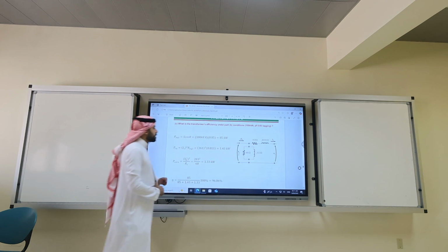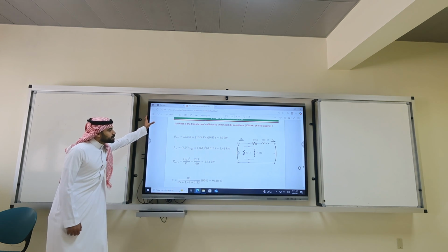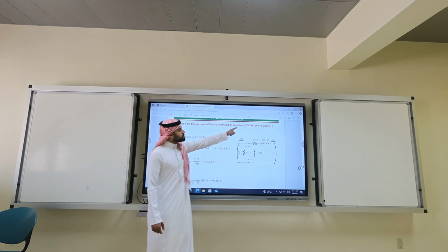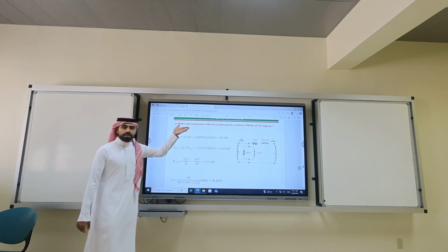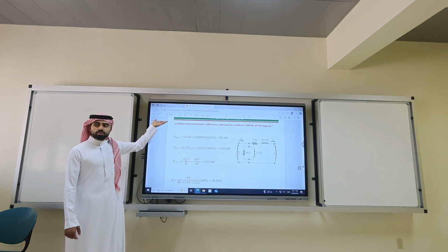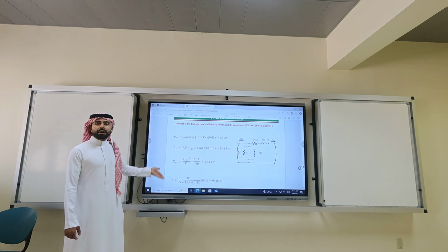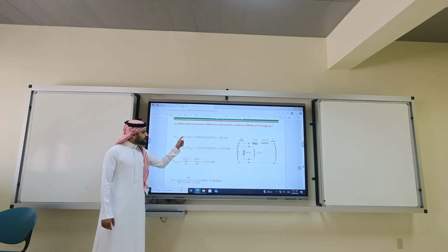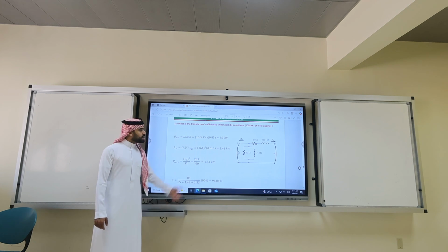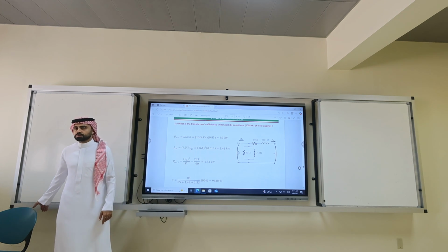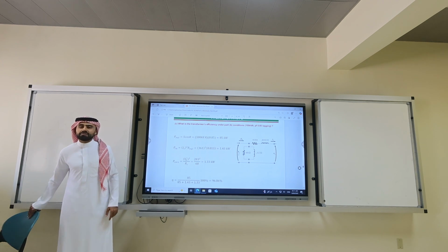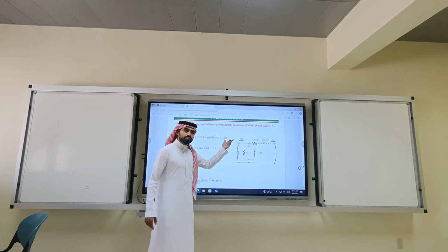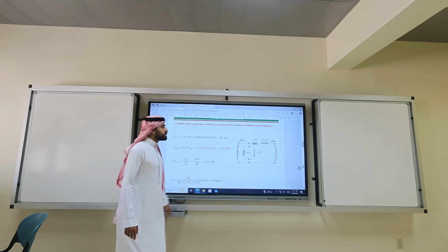That's one thing. To get the power calculation, if you read the question under these conditions, what is the efficiency? Efficiency always has to do with the real power. So we need to get the real power P output equal to S times cosine theta, where S is the 100 kVA. Cosine theta is the power factor, 0.85. So how many kilowatts? 85.